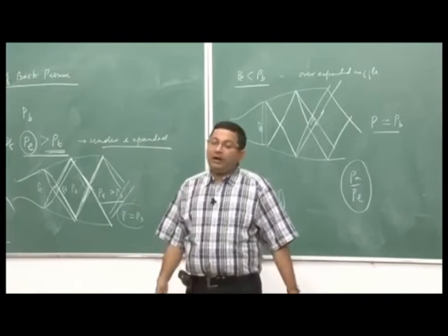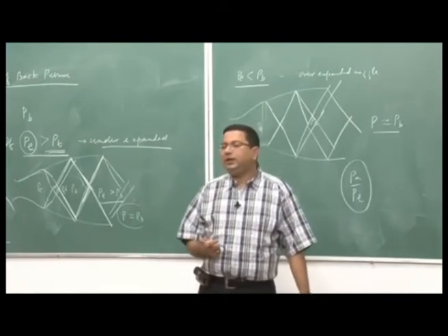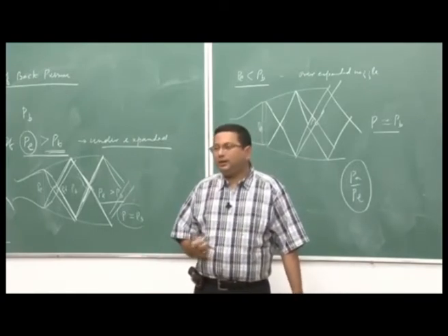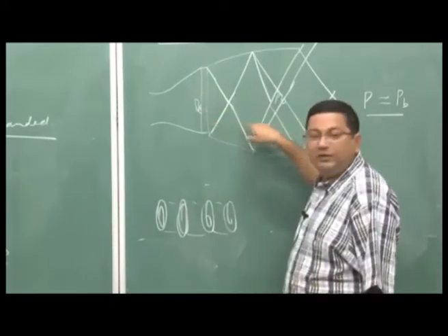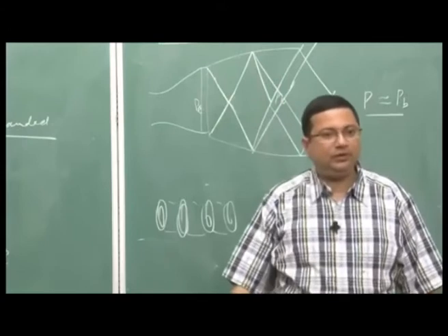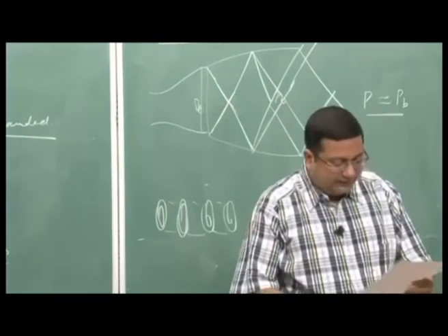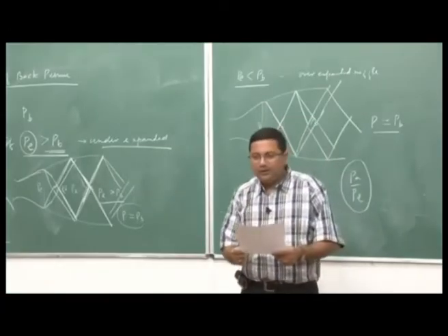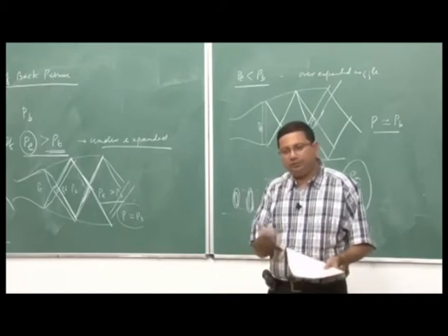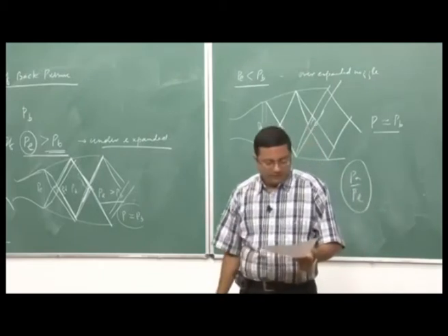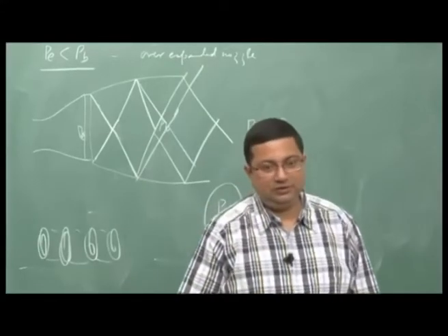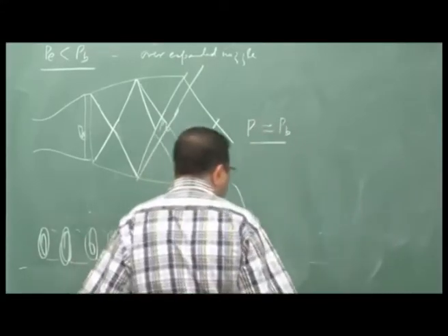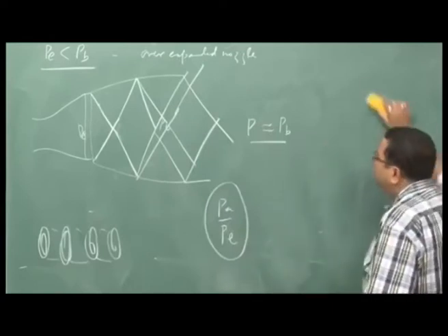Or another thing is that we design in such a way that we get the advantage of not having to deal with all these things, shock waves and all. So, that is the other designs which are preferred particularly for higher stages of rockets, which are plug nozzles or expansion deflection nozzles. So, let me discuss a little bit, not much, about those nozzles.